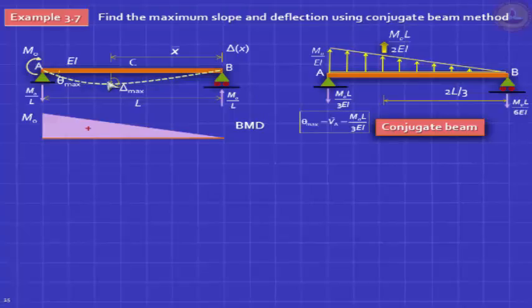Now, this is a tricky question, and this is not so easy to answer, because where is the maximum deflection? We don't know. If the question was find the deflection at midspan, easy. Just take 1/2 and quickly crack it. Anybody can do that. Where is the maximum deflection? I don't know. I know it's somewhere in the left half. That much I know, because that's how it will deflect. Where exactly? So I should know the distance either from the left hand or the right hand. Right hand sounds easier to calculate because your triangular loading is this way.